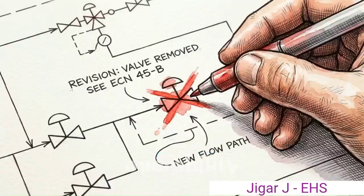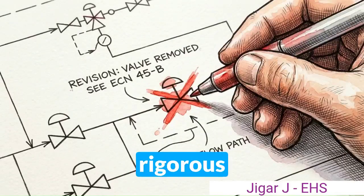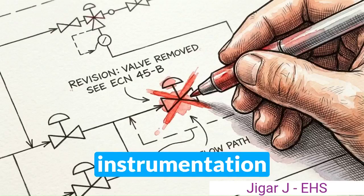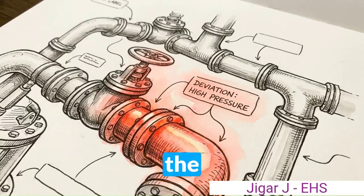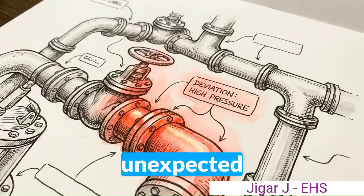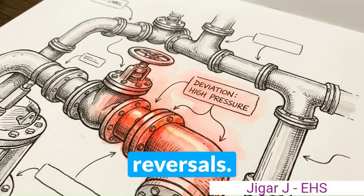Moving to the middle of the spectrum, where operations involve complex, interrelated chemical systems, facilities deploy a HAZOP. A hazard and operability study is a rigorous line-by-line engineering review of those finalized piping and instrumentation diagrams. The team applies guide words to the diagrams to search for operational deviations from the original design intent, like unexpected pressure spikes or flow reversals.